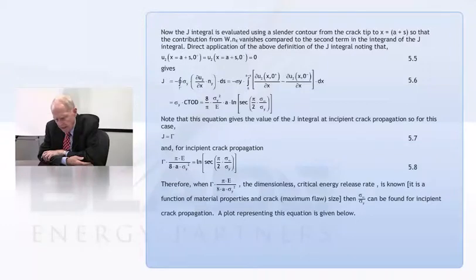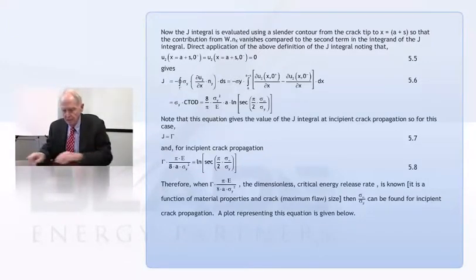I just want to mention a couple of things that ought to make it easy to understand it. And if you do that, then the whole thing just falls into place. Recall that this J integral was a contour integration, and had 2 terms. One was this W, this strain energy function, and let's talk about that term first.